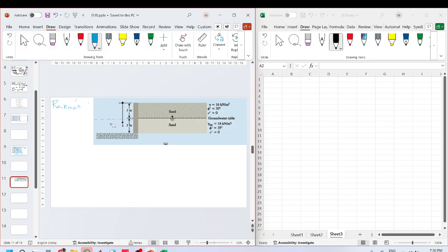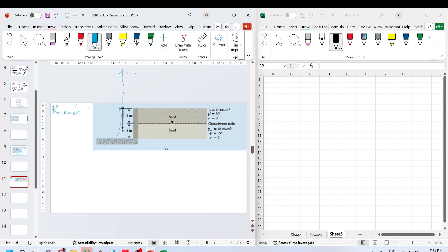But do you have any retaining wall without weep holes? Sheet piles have no weep holes, but every retaining wall will have weep holes. Yes, that is true. But what I think is happening here is, let's say 3 meters from the ground is your first weep hole, then you have another weep hole. Usually the walls are much taller than this. You will have weep holes at this level. Below this, there will not be any weep hole. So this will be the pressure here, isn't it?